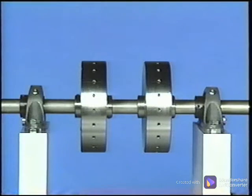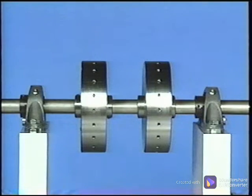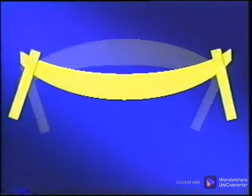Bent shafts fall primarily into two categories with very differing phase characteristics. One is a bend in the rotor between the bearings. The other is a bend in the rotor at the coupling. A rotor which is bowed between the bearings actually has an unbalanced condition, but exerts axial force on the bearings.